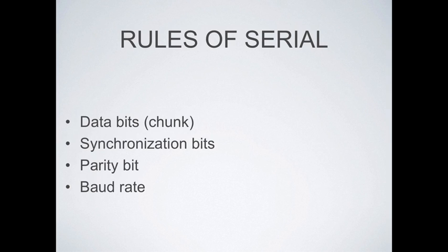And then there's some sort of clock rate, some sort of clock that's either pre-known or it's actually a wire that is sticking off of the serial interface. So if you're given a clock, that's awesome. If not, then you will have to start trial and error. Try to figure out at what clock rate device A is sending to me, and vice versa.